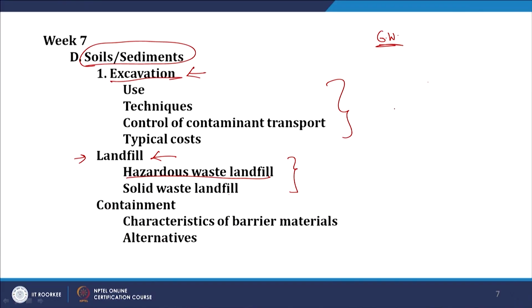hazardous waste landfill. Typically you need two impermeable HDPE membranes, as in you want to arrest the leachate reaching the groundwater, as in let us say a very generic figure here please, if this is my landfill, let us say, and obviously there are going to be different cases with respect to the cover. So, here again what do we need? I guess we are going to have two HDPE membranes here, let us say, and obviously leachate collection layer and clay layer